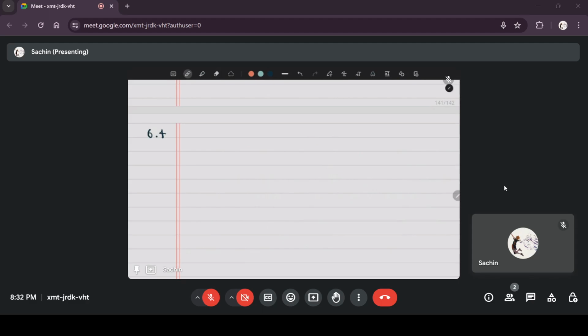Problem 6.4. The contents of a 4-bit register is initially 0110. So you have a 4-bit register. Okay, they aren't talking about any particular output here. The register is shifted 6 times to the right with the serial input being 101100.